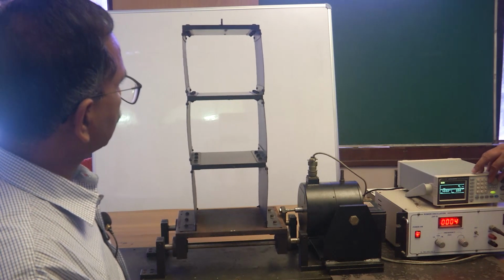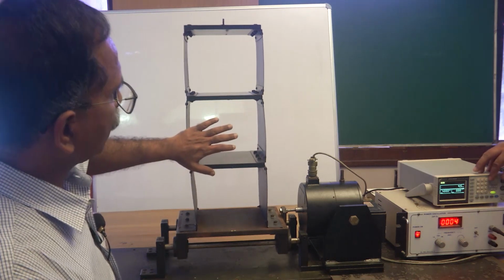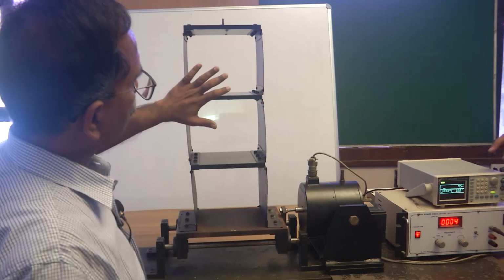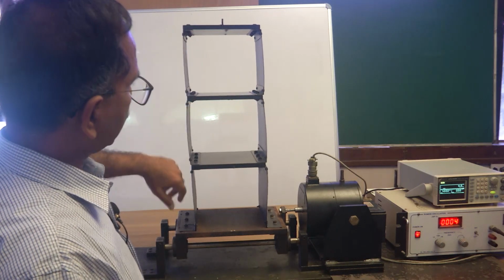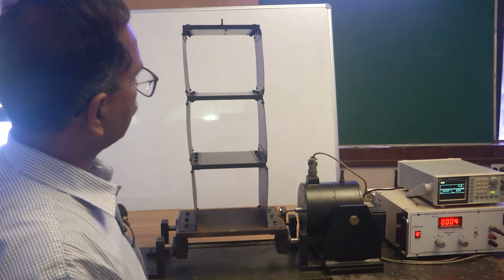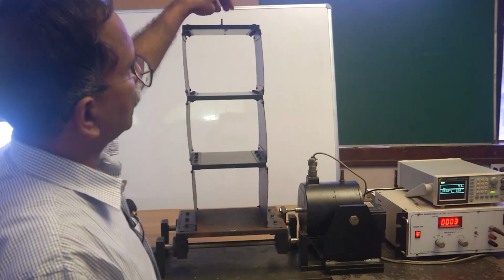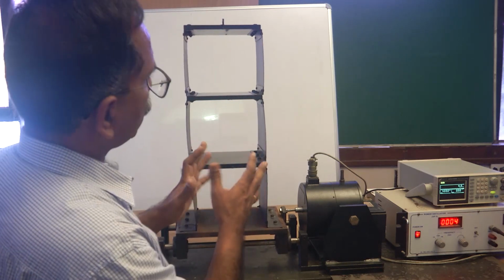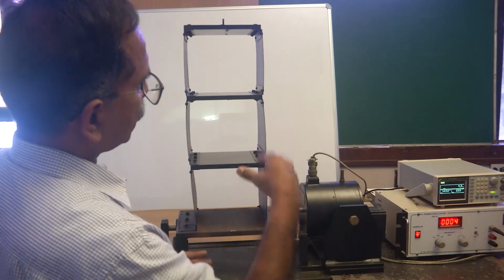Yeah, 4.4. So this is 4.5 hertz. Amplitudes are less as compared to at 4.3. Can you go back to 4.3? And probably here we expect large amplitude. So it's very difficult visually to confirm what is the amplitude, whether it is highest at 4.3 or 4.2. That we can find out by using a sensor and then taking the data. But visually, either 4.1, 4.2 or 4.3, these are the frequencies at which we are visually seeing larger amplitudes of vibration. Reduce it further.